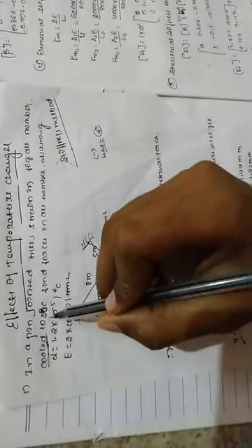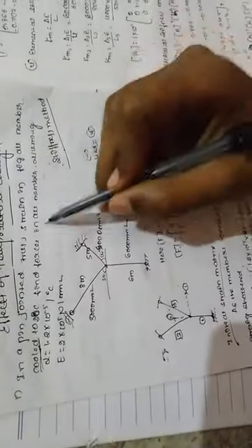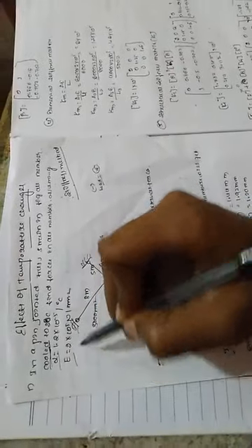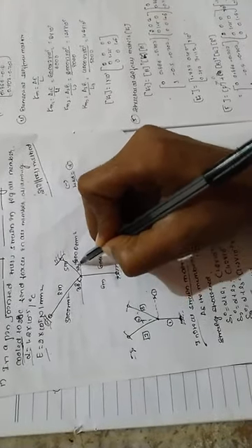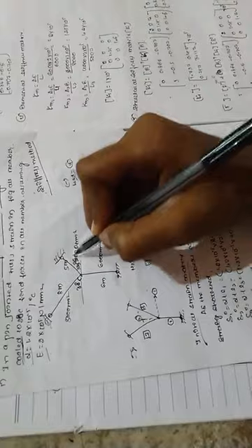In a pin jointed truss of the figure shown, it is given as cooled. If it is cooled, we consider it as negative. But if it is given as heated, we consider it as positive. So the members are cooled by 20 degrees Celsius. Find the forces in all members, assuming the given alpha and elasticity value, E value. So this is the given truss. You have three members and also given areas, and this is 45 and this is 30 degrees.